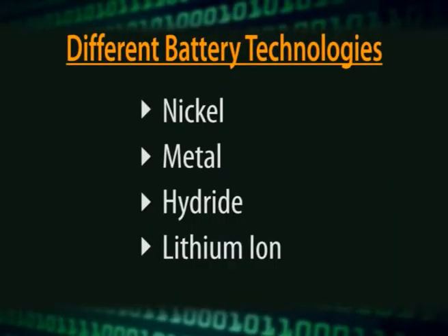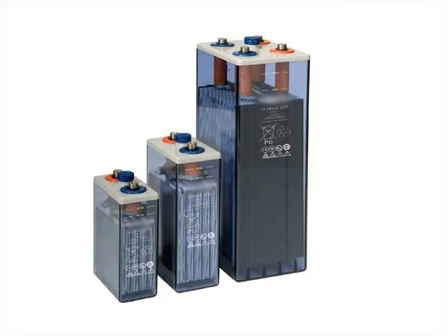Although there are a number of different battery technologies available, such as nickel metal hydride or lithium ion, unless custom manufactured, all UPS batteries are based on lead acid chemistry. The cost is one of the main reasons all the UPS manufacturers go for lead acid batteries. The lead acid batteries cost less for a given amount of energy than any other available battery type. Although this is the same chemistry used in car batteries, the car batteries and the UPS batteries are not interchangeable. Both are designed for a specific application.